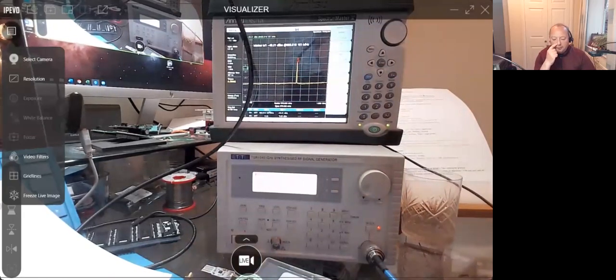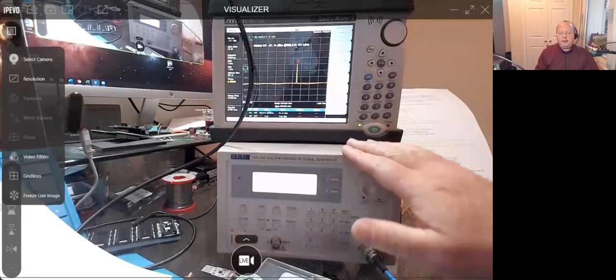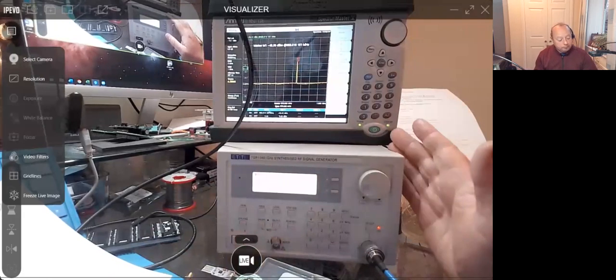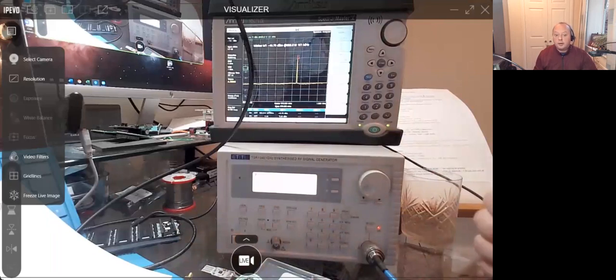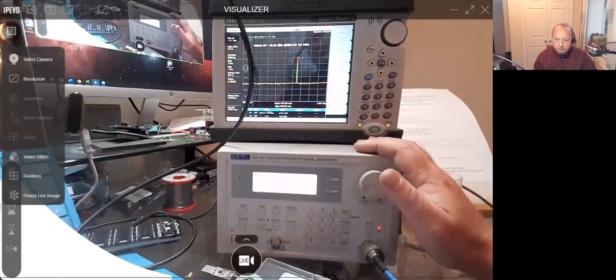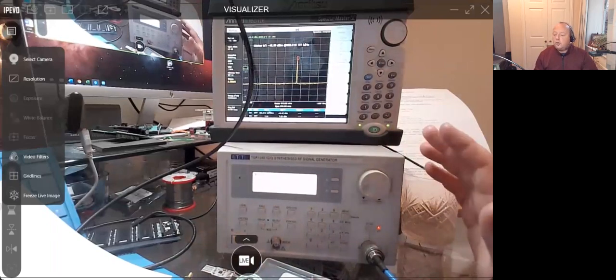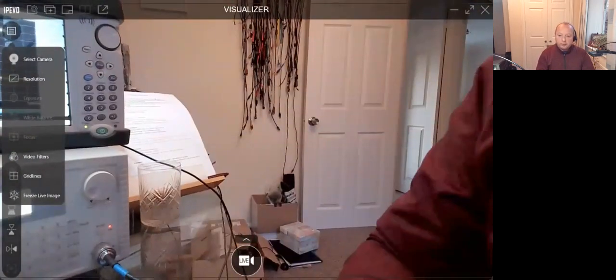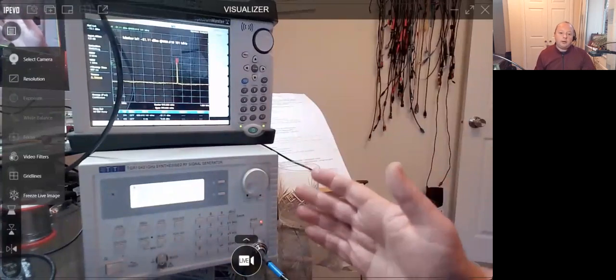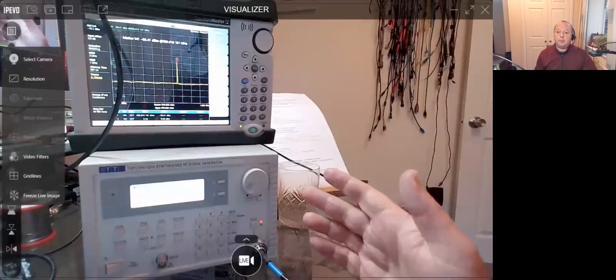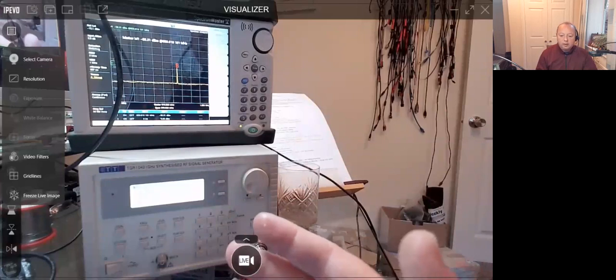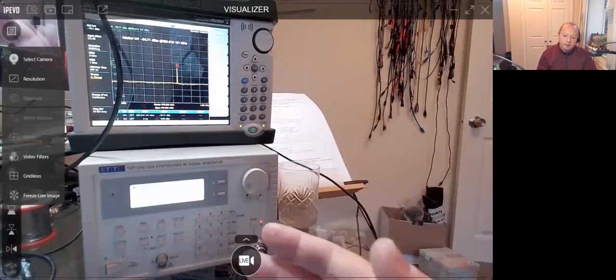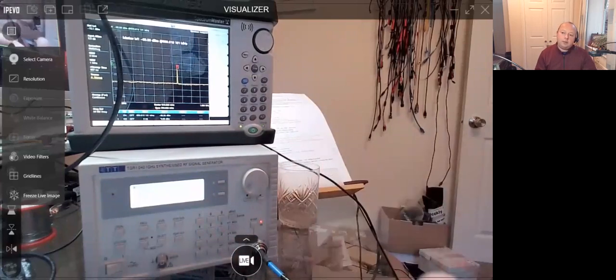Well, two things. One, I'm not 100% sure how to simulate the levels you might see at an EMC. For example, with something like a Raspberry Pi, it has to survive 3 volts per meter. If it's a medical product, it's 10 volts per meter. How to simulate those sort of levels with this, I'm really not sure. So there's a small caveat. If you're just using white noise, which is essentially every frequency you can think of, how would you know which band is causing you the problem? And how would you then fix it? Because if you've got a problem at 450 megahertz, that's a different capacitor solution to what you might have if you had a problem at, say, 1 gigahertz or maybe 80 megahertz.